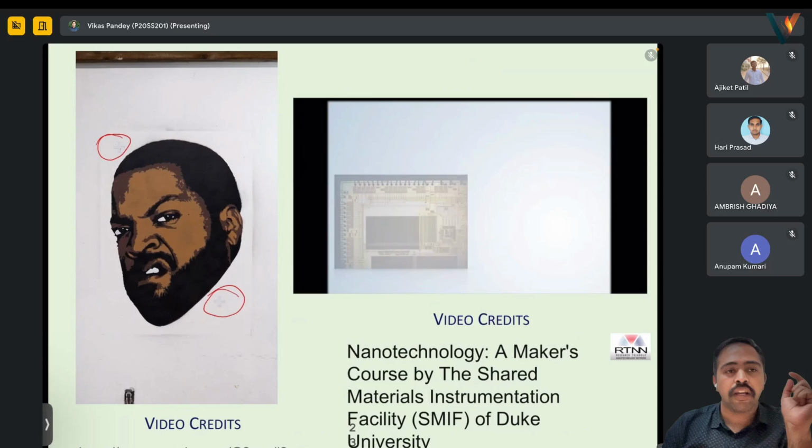Sir, is positive or negative resist commonly used in our research? Mostly positive, though some are doing negative now. Negative is preferred for lift-off. We are making and then depositing the pattern. In this negative case, we'll see later, when we develop, the photoresist profile becomes like this. This is the generalization, or they can vary, and these things happen.